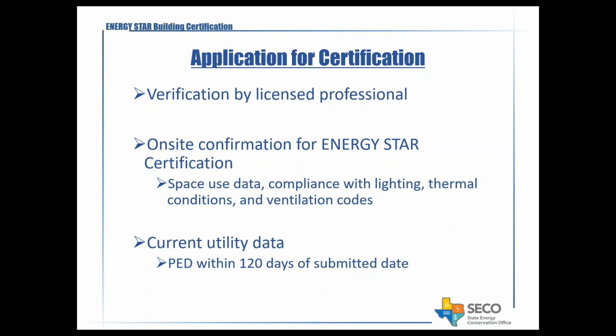So the on-site confirmation for Energy Star certification, the things that the representative or the professional are looking for, are the space use data. These are some of the details about your facility that were entered into Portfolio Manager. That could be the number of occupants there, the square footage, the size of the gyms, the percent area cooled, number of computers. Any various details like that are spot checked during the site visit.